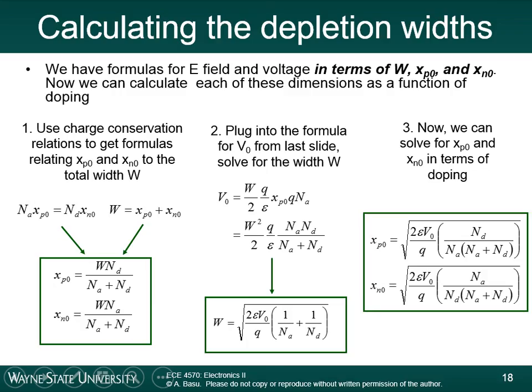The width of the junction is going to be entirely determined by the doping on Nd. So, a rule of thumb to remember, write this down: if you have what's called a one-sided junction, all the properties of the diode are determined by the doping on the lighter doped side.